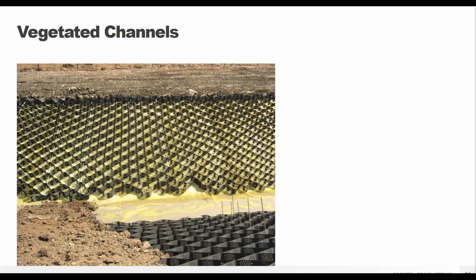And one last thing that I want to point out for vegetated channels, but for other infill materials as well, is that you don't necessarily need to cover the entire channel. You can just do the side slopes or the channel bottom if necessary. So that's pretty common with channels where you know that the bottom of your channel is going to have water flow through it all of the time, so it's already protected against that erosion, and you just want to protect the side slopes against water fluctuation.